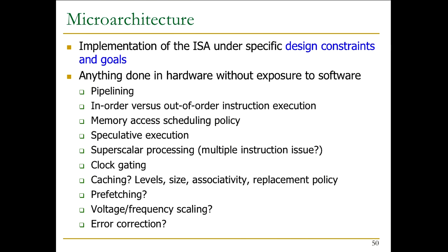Okay, clock gating. One of the ways of saving energy is gating the clock. Gating the clock means you basically make the clock zero so that your clock signal doesn't get supplied to a circuit block. For example, if you're not going to use your floating point unit, you can gate the clock to it such that you don't consume any clock power in it. Is that part of the microarchitecture or the ISA? Well, that depends on who does it, right? If it's done completely in hardware without being exposed to the programmer, then it's part of the microarchitecture. Today, most of it is part of the microarchitecture, actually.